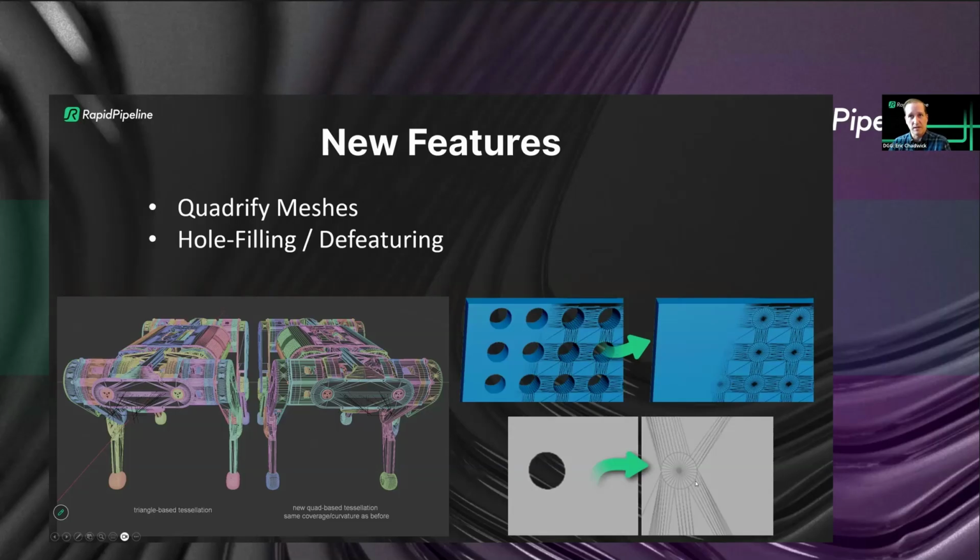And a cool thing about it is that it interpolates the UVs from the surface to the hole itself. So now the hole has the same, continuous UV with the rest of the surface. And you can also interpolate the material values so it would use the same material as the rest. But it's up to you. You can choose to have a different material on the hole or not, or having them be separate objects and not be integrated into the main surface.